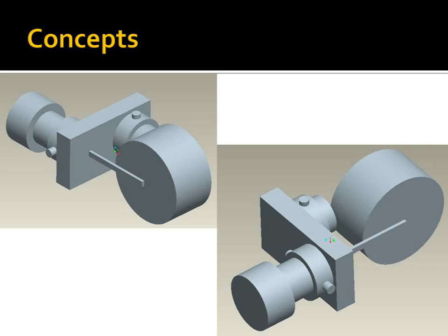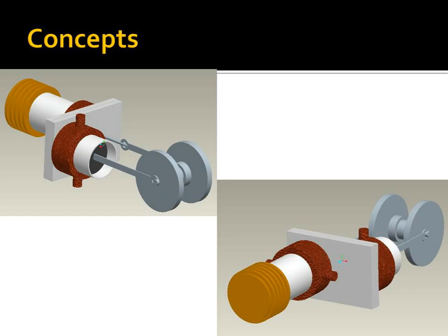exposed to the solar radiation, incorporating a cooling jacket around both cylinders to lower the temperature of the cold source, therefore increasing the efficiency. This is a gamma type configuration, and also replacing the tubular regenerator style with a manifold plate regenerator, where you'll see hopefully in the diagram in the next few slides that the regenerator will incorporate micro channels. So this is the third and current iteration of my Stirling engine.